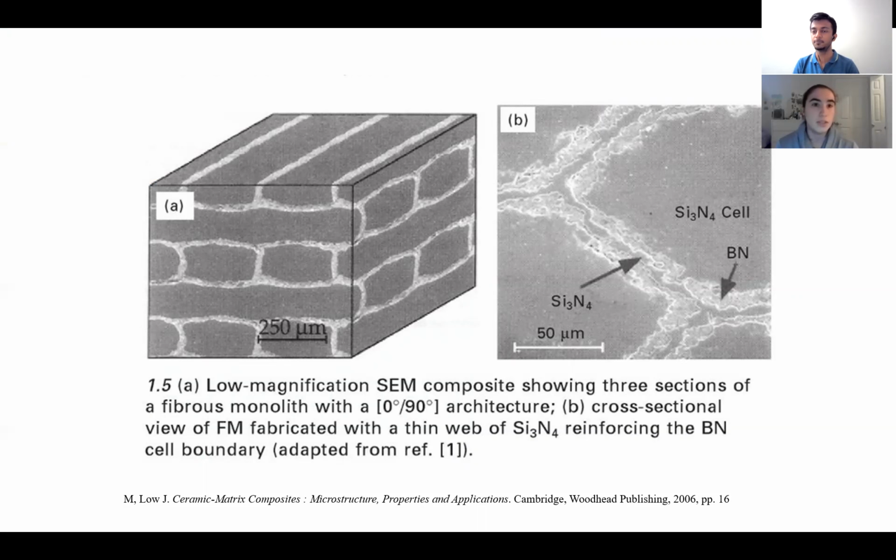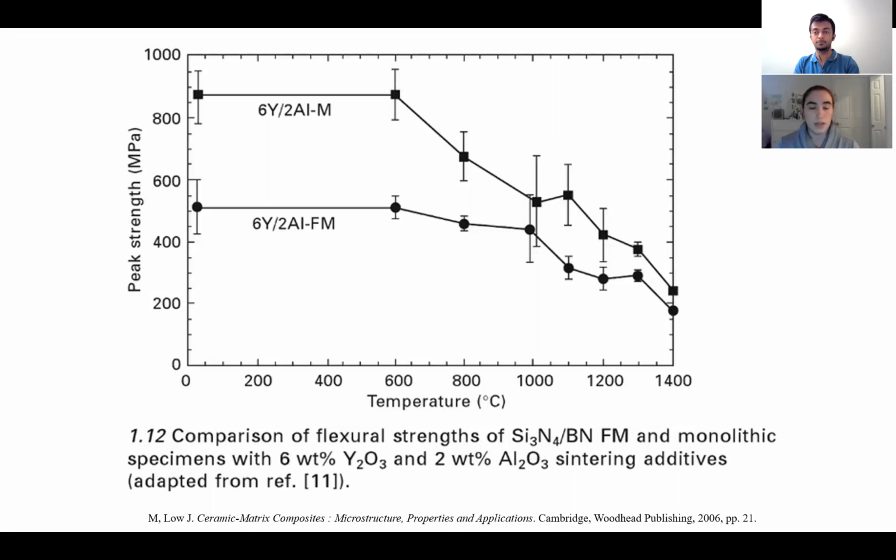These are images of the microstructures of these CMC materials. You can see that they're oriented fibers embedded in matrices, and the phases that you see depend on what you put into them. So CMCs can be made out of a lot of different materials, such as carbons, silicon carbides, aluminum nitrides, silicon nitrides, that all have different functions based on the composition. This is another chart that shows how they retain their strength up to and above 1000 Celsius to 1400 Celsius.